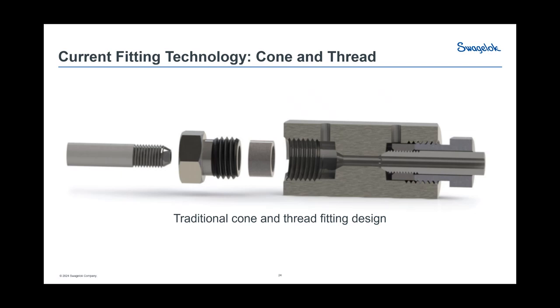The best way to see this is if you go to an oil and gas facility where there's a whole panel of these on a wall, you look under the panel, and there are always going to be pig mats. Those are the mats that we put under to collect oil. They're under every single one of these things because they're dripping oil. Now, a drip of oil is not very much volume, but that would be a heck of a lot of volume of hydrogen. So not recommended for using this as a standard component in hydrogen.